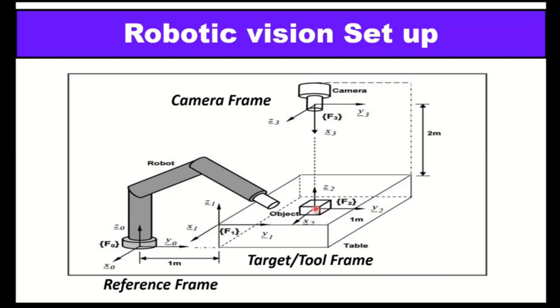So this is our target frame. So your tool or actual gripper is moving in 3D space, that is XYZ, and it is always trying to map the object frame. To do this, all these movements of the joints and links must be done, and they are with reference to the reference frame. This is what is called frame mapping.